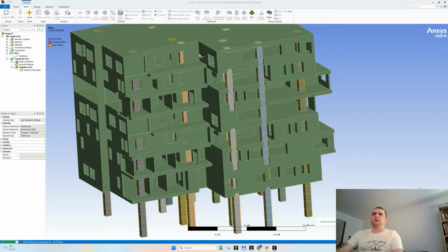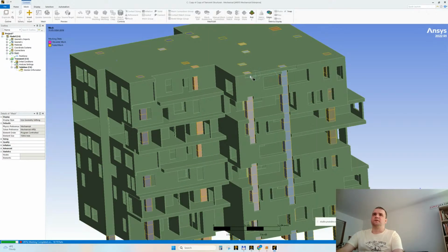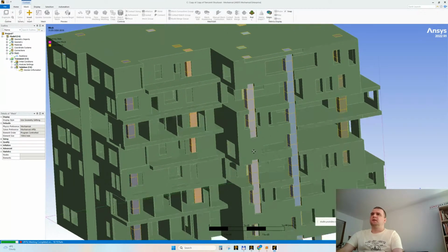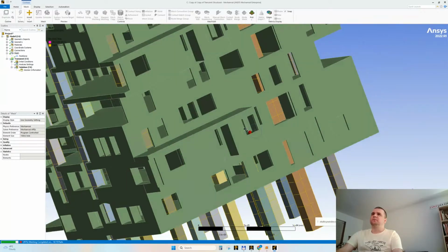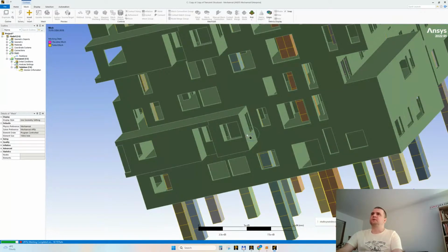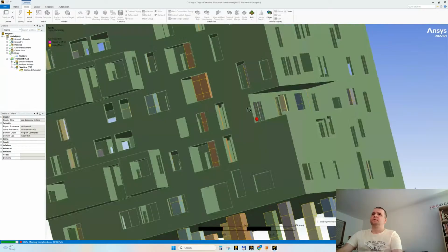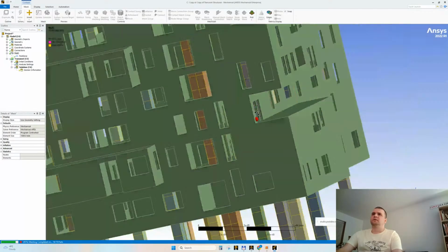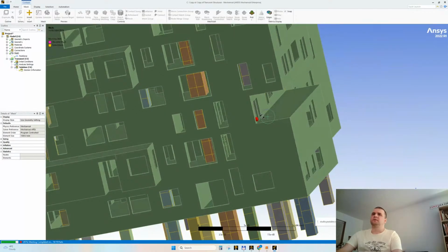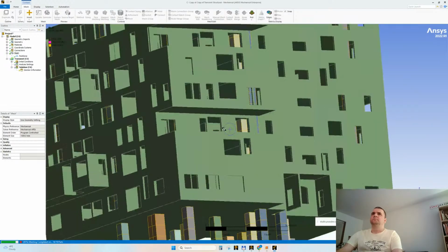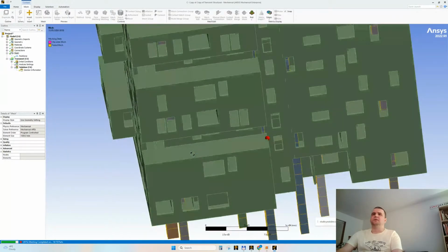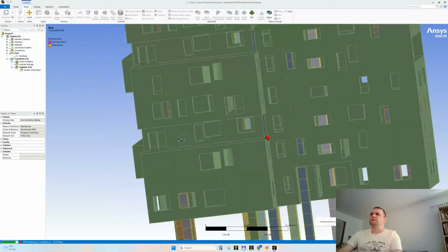So we should remember, if we have such recesses like here, some grooves and channels, then we will have problems, you know. Here we have problems when we want to obtain a coarse mesh. So this is why you need to always pay attention since the modeling stage.